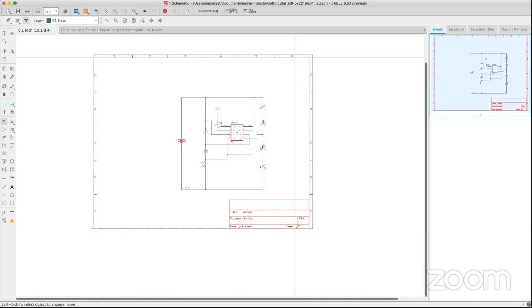If you have multiple schematic sheets, EAGLE will be able to let you know by using the label function. It will let you know in which sheet that signal came from and which area it's located. So yes, it documents the schematic. That way you could see the transition of a signal from sheet to sheet. So it is a really good idea to always use a frame. I strongly recommend that you always use a frame.